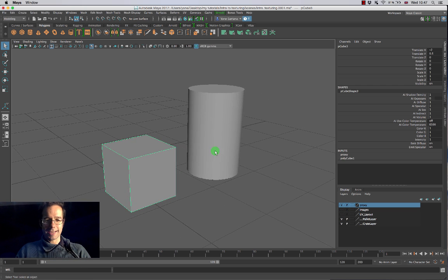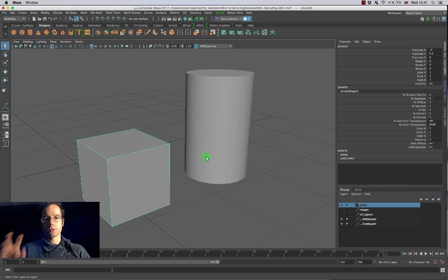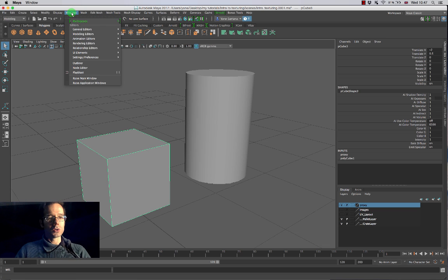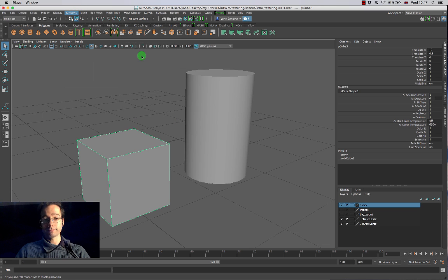and I'm going to be working on a few objects at a time, and I'm going to start off with the most basic shapes over here. Now, when we're going to add textures to objects, we're going to start working with two tools mostly. One of them is the Hypershade, which you can either find in this button up here, which is nice, blue and round, or I can go into Windows, Rendering Editors, and Hypershade inside of there.